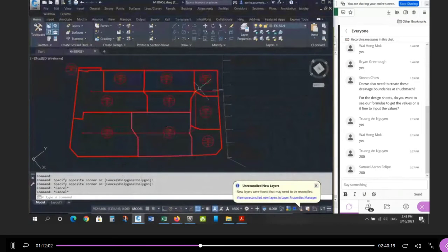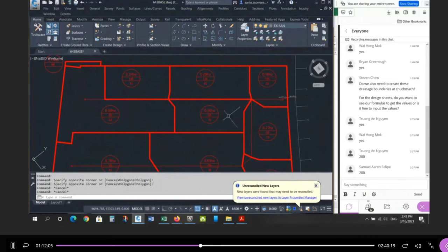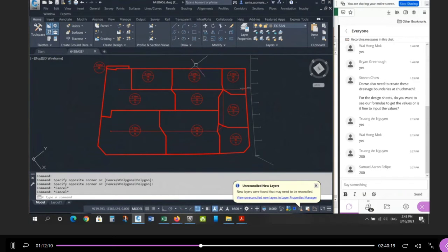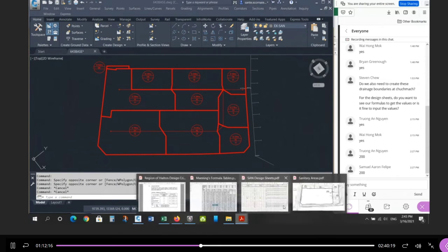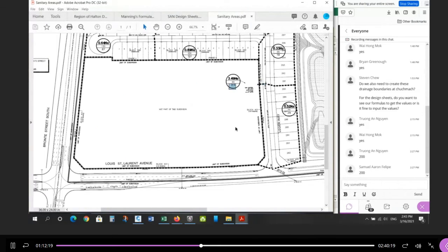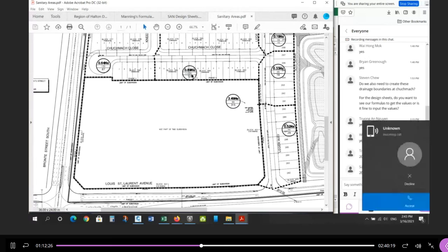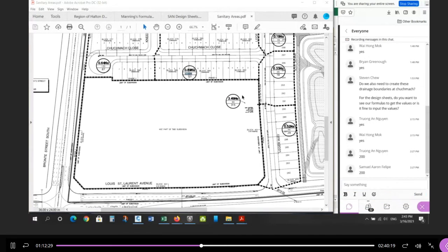And if you want to check the math, you can, right? 33 plus 40 plus 22 plus 15 plus 30. These are my areas, right? You're going to have slightly different populations depending on how you drew your drainage areas. If you add up the total population here, you should get something less than 315. Okay, why? Because I'm using 135 for the townhouses, but I'm using 55, less than 90, for most of the subdivision. Right, so I'm expecting a much smaller total population for residential than I am for this commercial property.